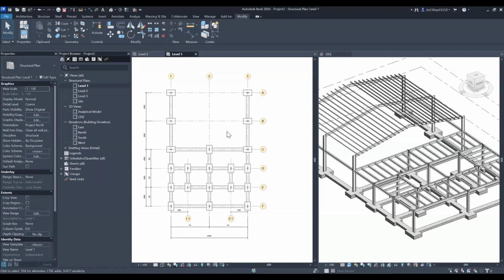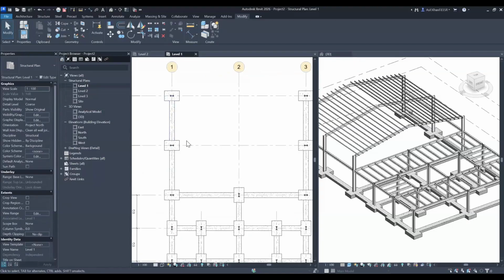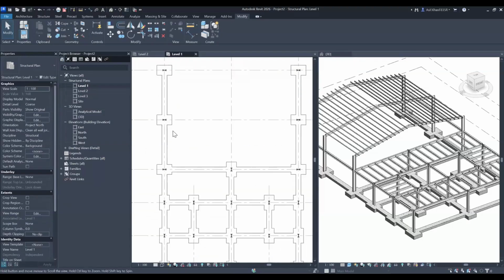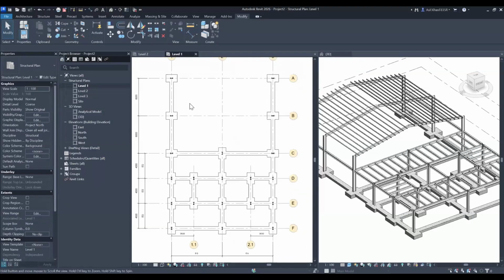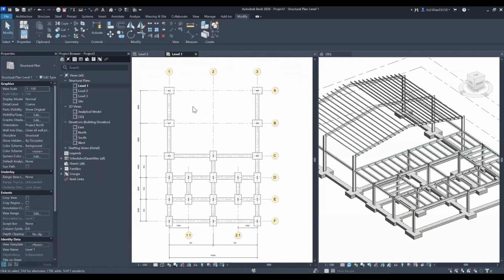Now, we don't say this marking over here in AutoCAD, in Revit, we say tag. In AutoCAD, if we have to mark this element, then we'll be putting some text, writing down, then copying from one place to another, putting again some text for the foundation, for the beams and other stuff, and that's just too much work for me. So instead of this, what we can do in Revit, we can tag them all.